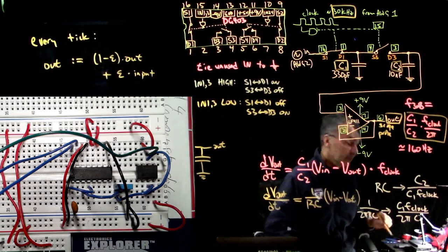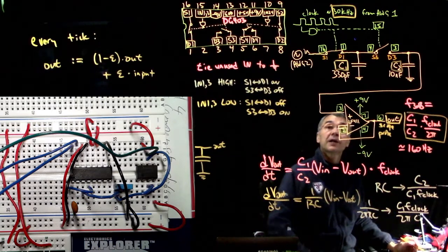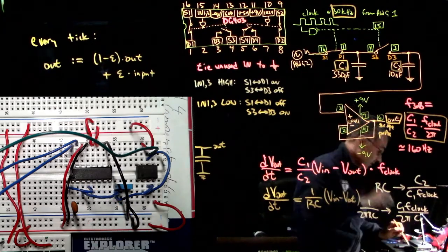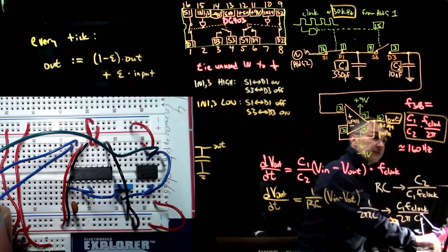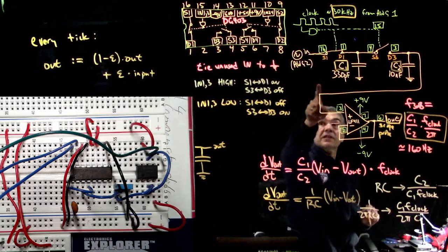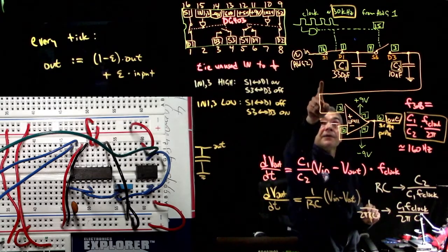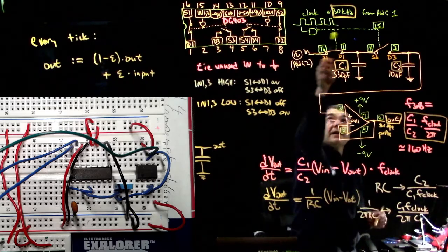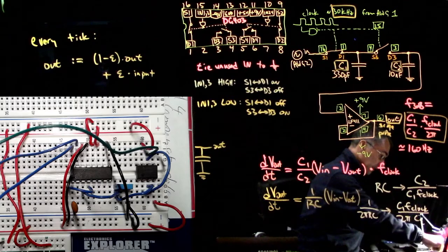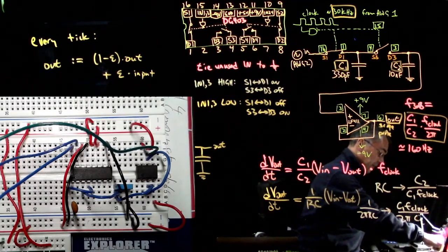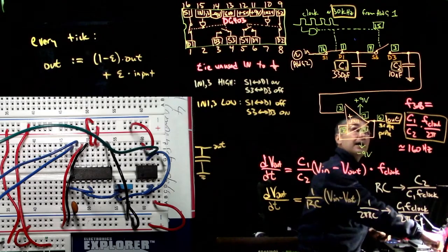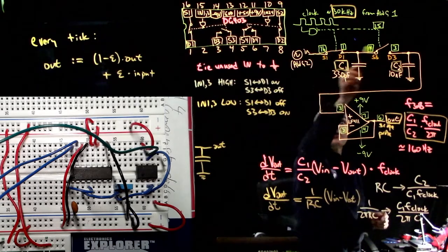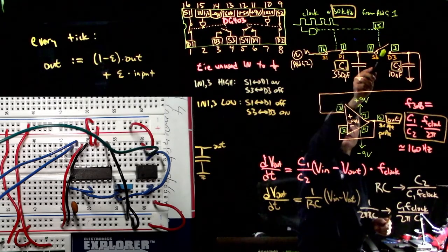What did we plug in? Waveform generator number 2 is coming into pin 16, so that is this wire right here, top left corner of the chip, the DG403. Then pin 15 is AWG number 1. That is my clock signal, and I'll show you that in a minute. Remember, pin 15 opens and closes both of these switches. If this one's closed, this one's open, and vice versa.